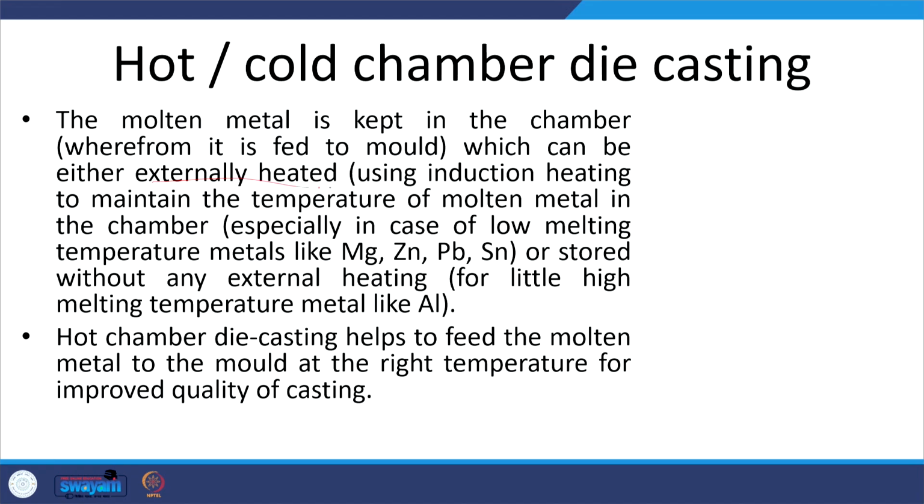The molten metal is kept in the chamber from where it is fed to the mold. It can be externally heated using induction heating to maintain the proper temperature of the molten metal, especially for low melting point metals like magnesium, zinc, lead and tin. Or the molten metal is stored without external heating, and the pressure is applied directly for feeding the molten metal into the die, the metallic mold. This is used for somewhat higher melting temperature metals like aluminum.